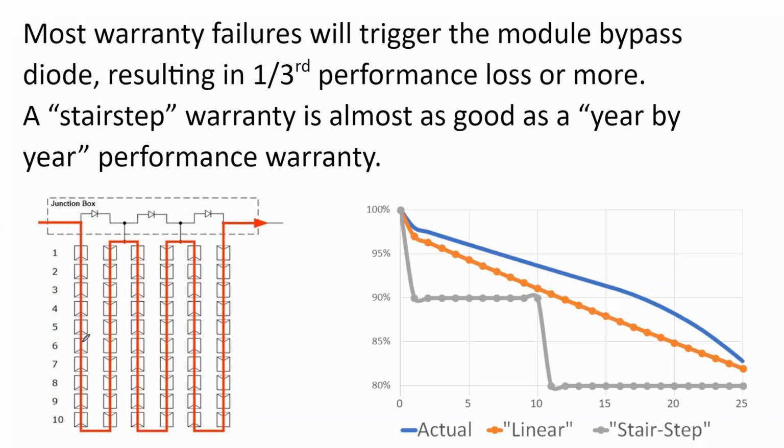And what happens when a solar panel fails is, for whatever reason, somewhere in the panel there's a defect. Maybe it's a little soldered connection point that blew apart with thermal expansion and electricity, or maybe some water got into the panel and it got between the cell and the surface of the module, and the voltage vaporized the module and left behind some particulate, and that led to some corrosion and it corroded the solder point. We could come up with a lot of theoretical reasons. There's something wrong at that point of the module.